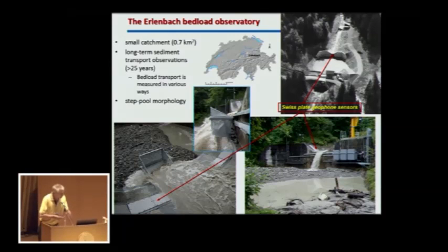We have now more than 20 years of measurements with this sensor or a similar sensor. And for the last few years, we also have these 3 metal baskets installed here at the large check dam, so we can take reliable direct bedload samples and compare them with the signal of the geophone plates.